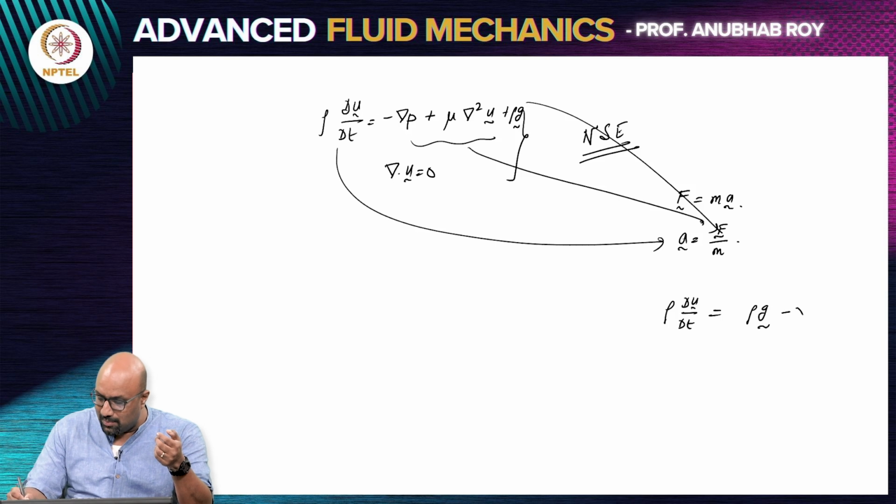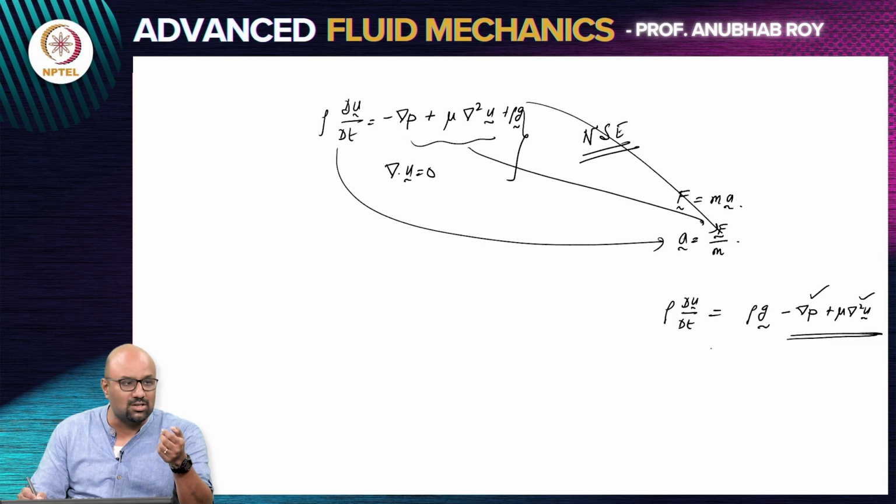The problem comes in with the additional terms that you have in your equation. The term that comes from the surface forces, precisely pressure and the viscous component, because writing this in a Lagrangian coordinate is very painful. This is a pressure gradient.